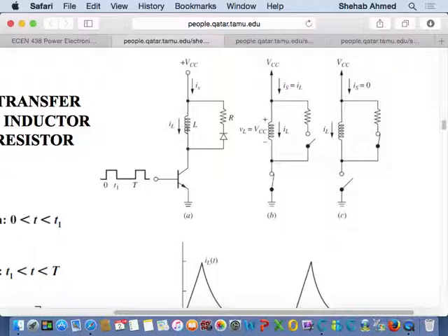But I know that the inductor was charged. There is energy stored in the inductor, half L i squared. It's there. And where will it go? If I did not have an alternative path for it to go, and I open the switch, it will just arc across the switch, and the inductor energy will be dissipated in that arc. After the arc energy is dissipated, that's it. The switch will open, right? Theoretically speaking, if it doesn't burn down. But in power electronics, we don't do that.